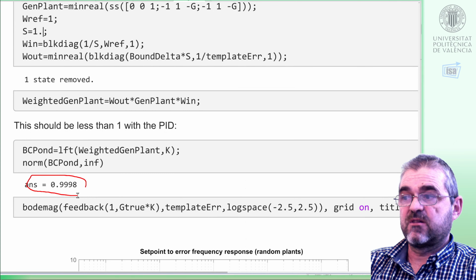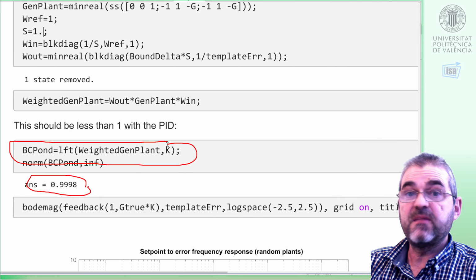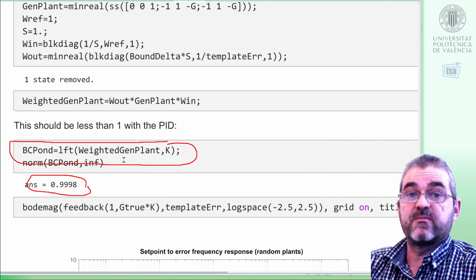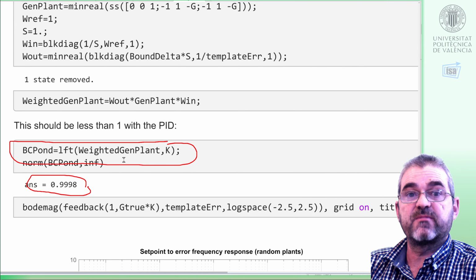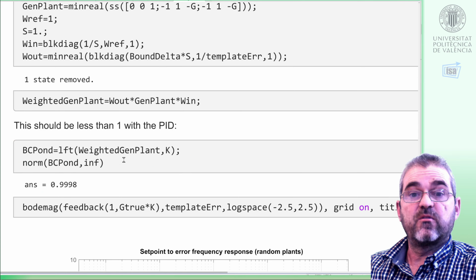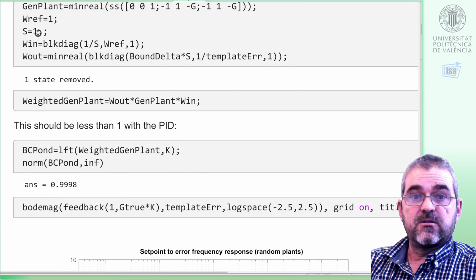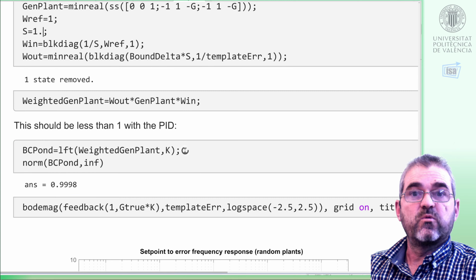Also, this number can be made smaller by using a controller that, instead of being a PID, minimizes the closed loop H-infinity norm, so an optimal H-infinity controller. Indeed, this is what is done in most applications, but for brevity we will leave playing with the multiplier and with H-infinity controllers for a forthcoming video. For now, we'll stop it here.